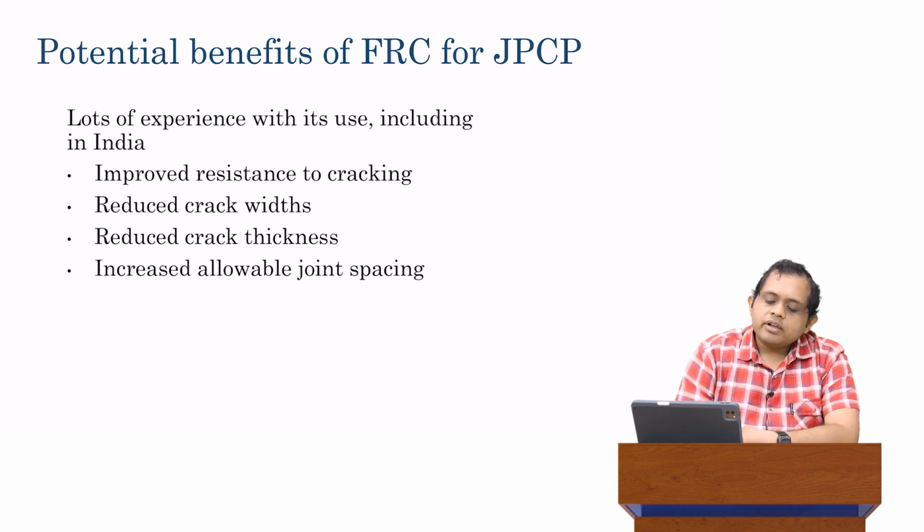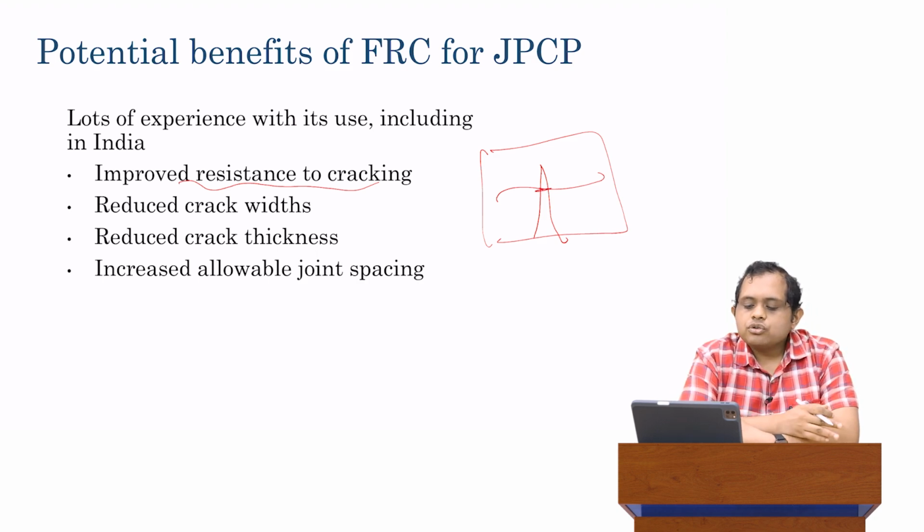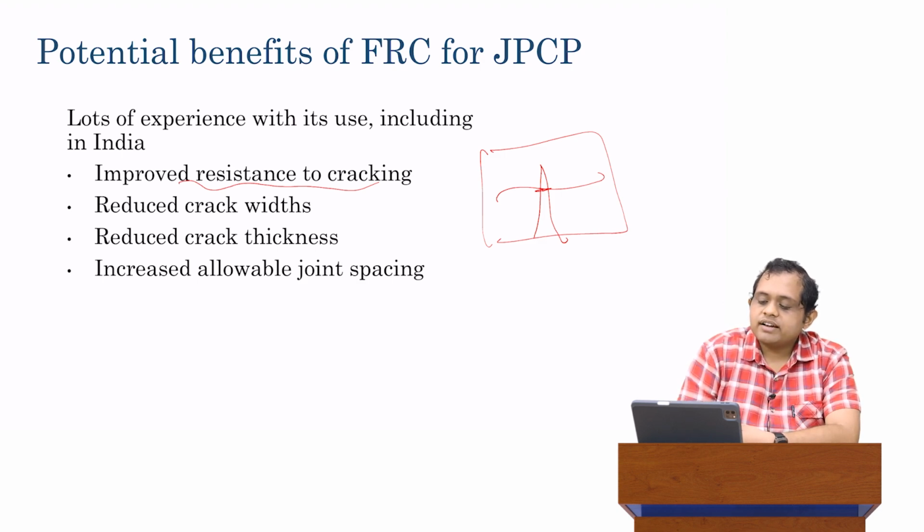It has been found to have improved resistance to cracking. That I think was already quite clear, as I pointed out previously that when you have this fiber and a crack is trying to propagate, it arrests the propagation of the crack. So there's improved resistance to cracking. That then leads to reduced crack widths, because of this arresting of the crack, the crack width can only grow that much, and then beyond that the fiber is preventing the crack width from increasing.